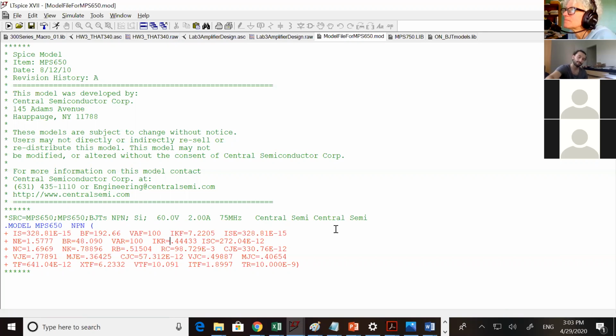How did you know that 1 over gm was going to be smaller than all those other resistor values? So gm is often 0.1 to 0.01. So 1 over gm should be something like 10 or maybe 100. And for ro it's VA over IC.